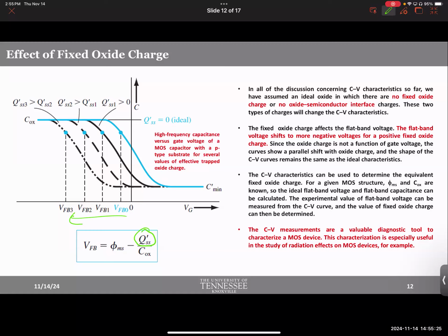So people do a lot of characterization, and somebody noticed that, based on how much trap charge you get, you have a fixed amount of shift in the CV. And we could back calculate and tell you how much fixed charge is there. And based on that, you could calculate the flat band voltage. Am I making any sense at all?